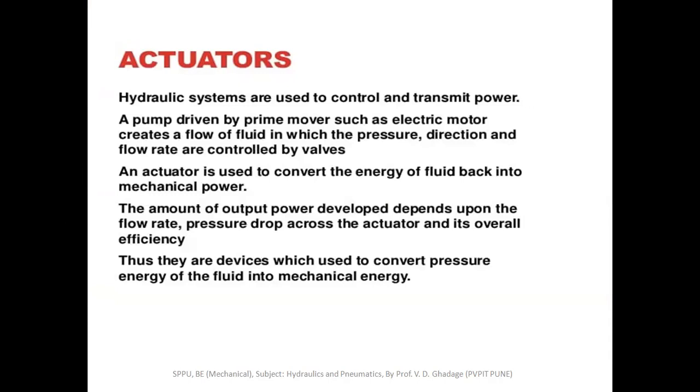In hydraulic systems, actuators are used to control and transmit power, meaning we control the hydraulic system and transfer the power. A pump driven by a prime mover such as an electric motor creates a flow of fluid in which the pressure, direction and flow rate are controlled by valves. An actuator is used to convert the energy of fluid back into mechanical power.